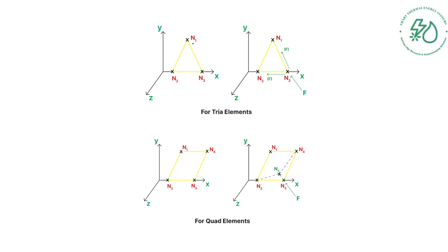When you use three-edge tri-elements like that, when a force is applied to the node N3, there are only three nodes available to define that plane. To define that plane, the XY plane, you need 3 points. So when F is applied to N3, N3 cannot bend or move in the YZ plane. So it is going to transfer the load to N1 and N2, as you can see.